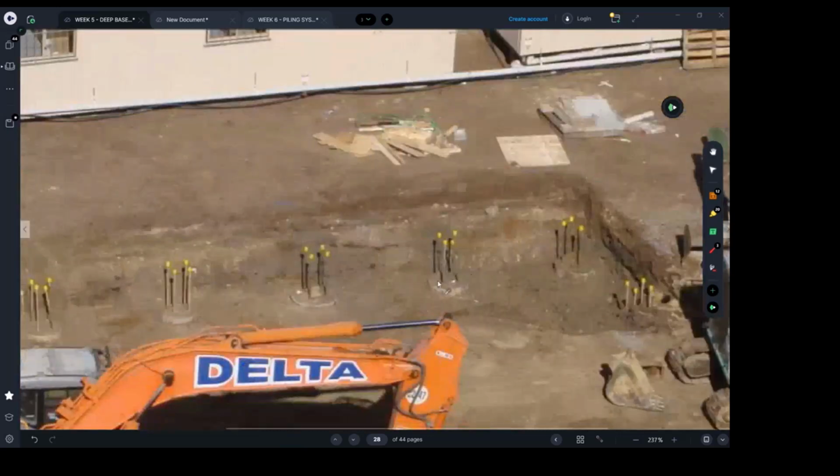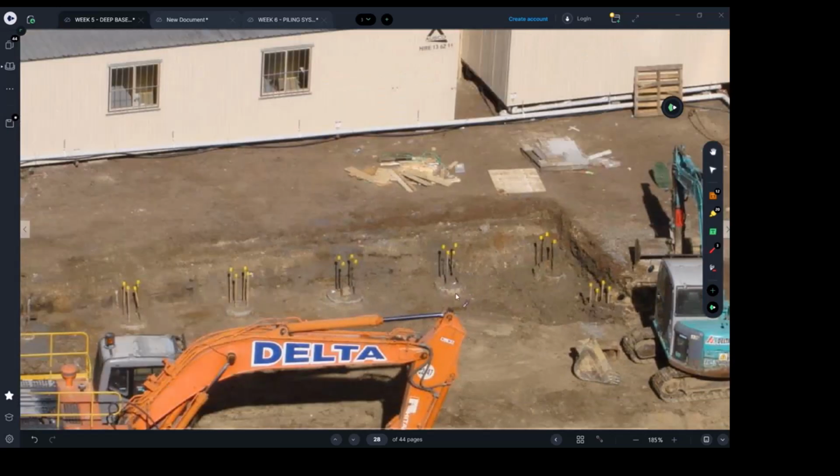We're going to see next week sections talking about the construction process and the equipment used and all these kinds of things. It's just going to be too long to give it to you in one day. But today, make sure you're understanding the process. What's built first, right? First, we dig the hole. Second, if we are not using the bucket drilling example, the bucket drilling example means you're digging a hole for 3-4 meters, putting the reinforcement, pouring the concrete, and all done.